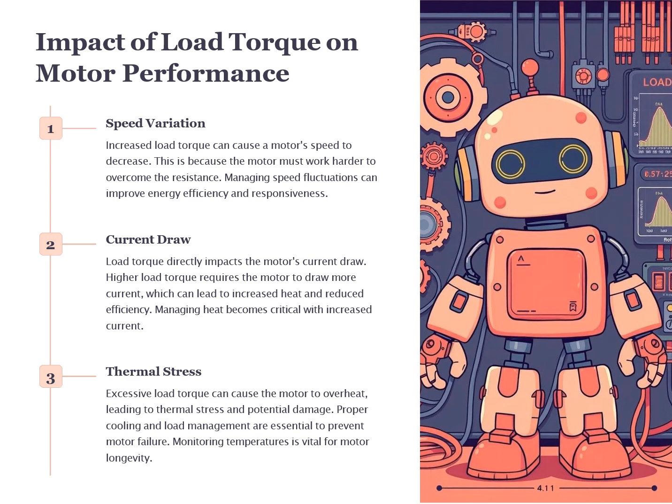Now, what about the current drawn? The current drawn is another critical factor. Higher load torque requires the motor to draw more current, which can lead to increased heat and reduced efficiency. Managing heat becomes essential, especially in high load applications, to prevent motor failure.